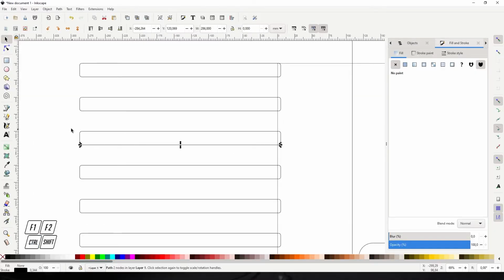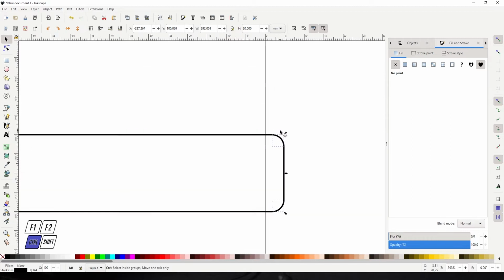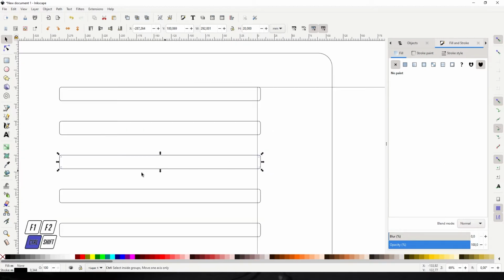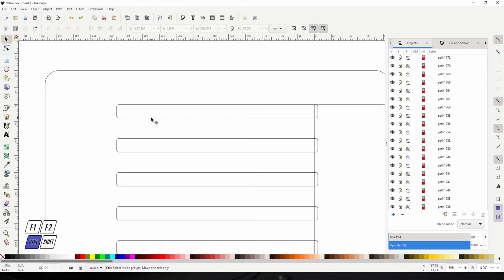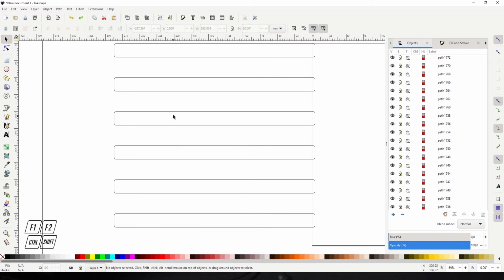What I have to do is to join, in this case, these 8 lines, 4 lines and 4 quarters of circles, to get a closed shape. Because as I mentioned in the beginner tutorial, the Shaper Origin needs closed shapes to be able to recognize what is an inside and what is an outside cut. And my workflow for rejoining these shapes is as follows.